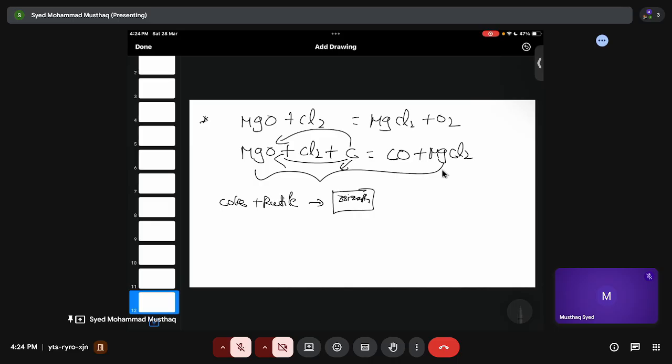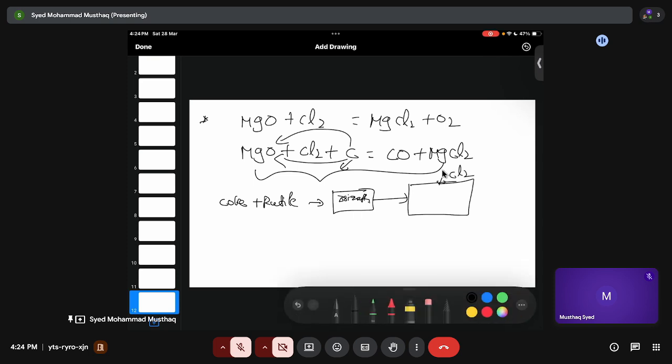with the chlorine. You are involving the chlorine because our goal is to form chlorides, right? So now you are adding chlorine into the reaction, and this chlorine will react with the briquettes or the TiO2. That will result in the formation of carbon monoxide and titanium chloride, right? It happens mostly at 800 to 850 degrees centigrade. So here you do fluidization.